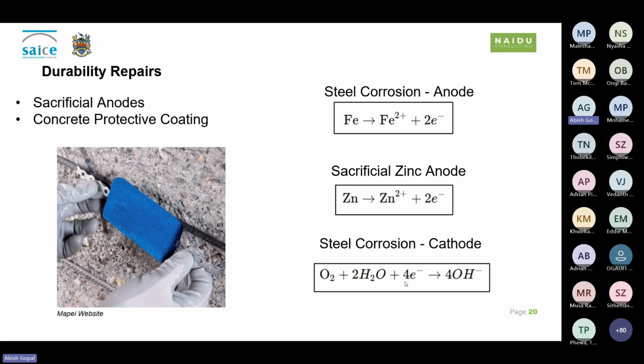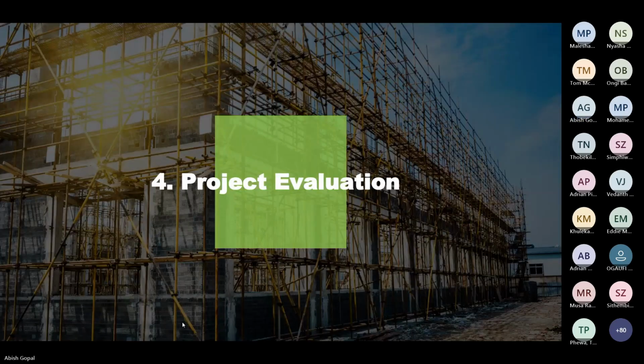Additionally, to protect the concrete surface, a hydrophobic impregnation and silane additive was used to create a barrier against water and chloride ingress. This was also mentioned to Vakili as well. And lastly, we performed a project evaluation on the Mzimkhulu River Bridge. This is utilized to guide us as Naidu Consulting to determine shortfalls and to better improve our response on these types of projects.